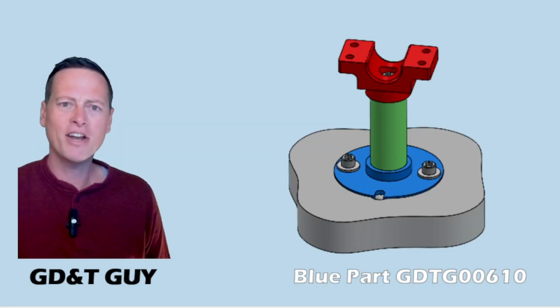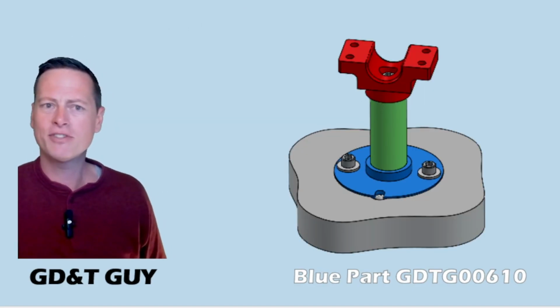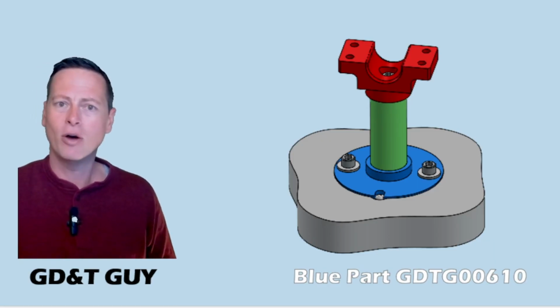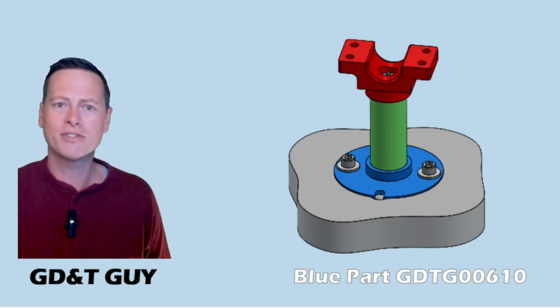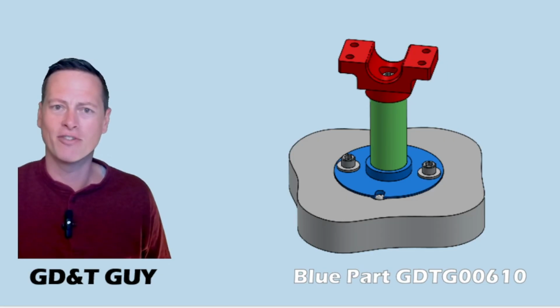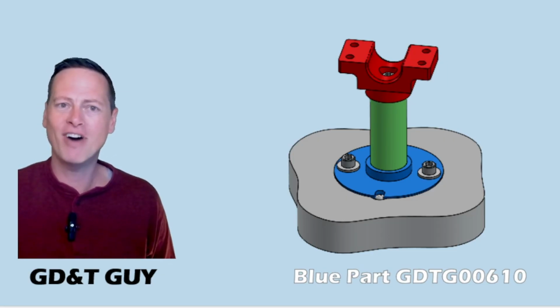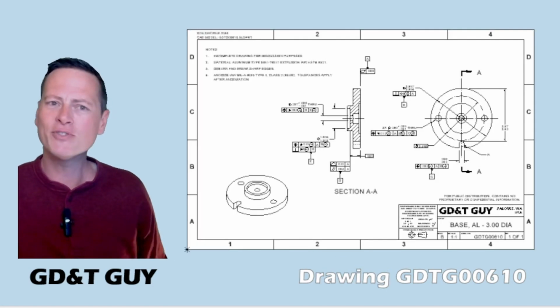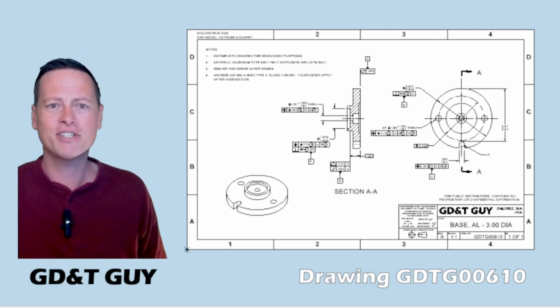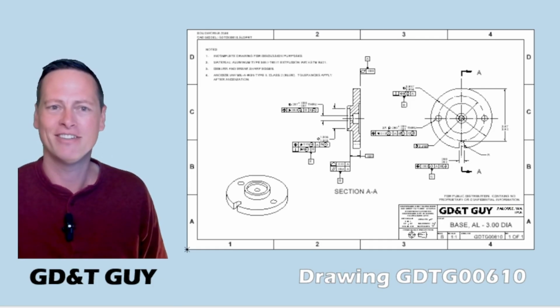These will provide a lot of constraint for this part, and for the subassembly too. Hopefully these are derived from the requirements of what we need this device to do though, right? It's pretty well locked in, which is, I guess, what we want. Now for this version of the blue part, and for a lot of parts, the datum feature selection can be pretty obvious, at least where it interfaces to the gray plate.